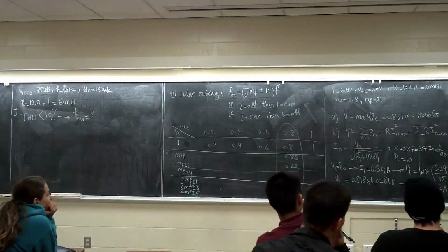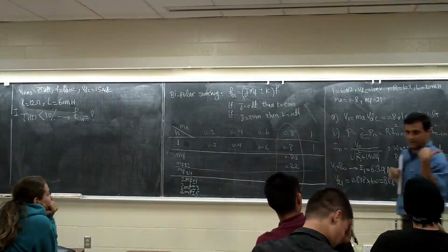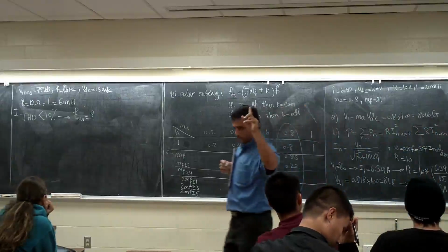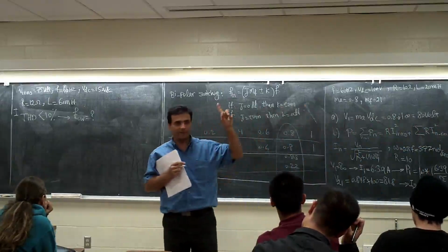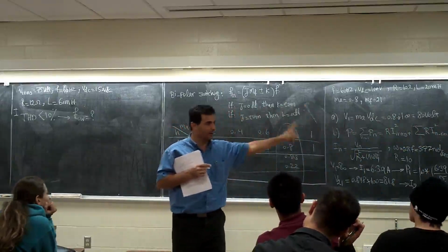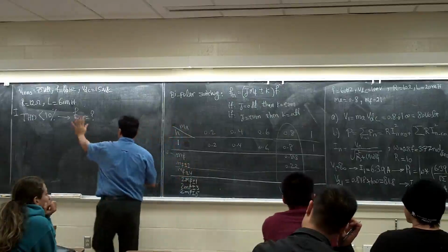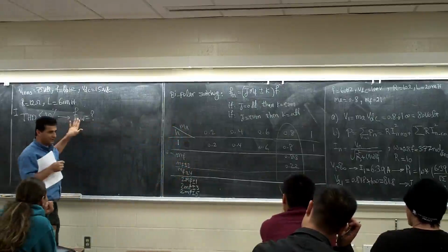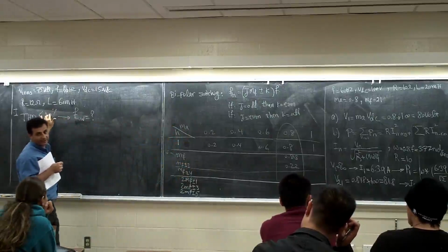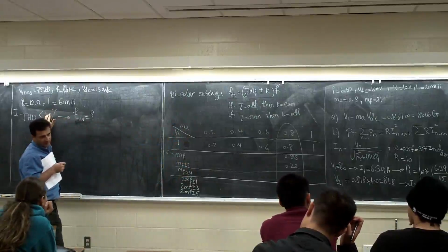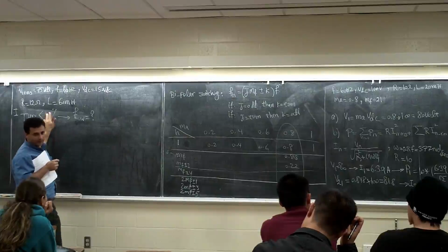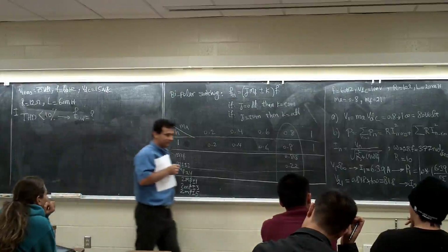So you can see the relation between the switching frequency and the THD. If I go higher on the switching frequency, or I will have a higher MF, I'm going to have a lower THD, right? That's the reason he's asking you, what switching frequency should I select to have a THD less than 10%? Usually they say less than 5%, not 10%. But this is an example, that's normal, right? So now let's go back here.